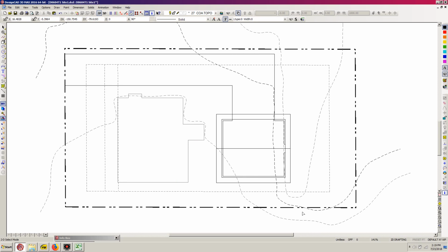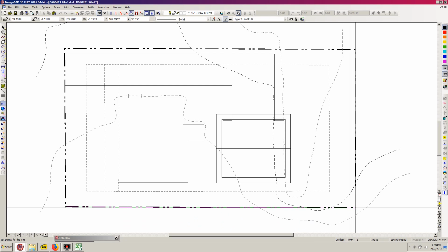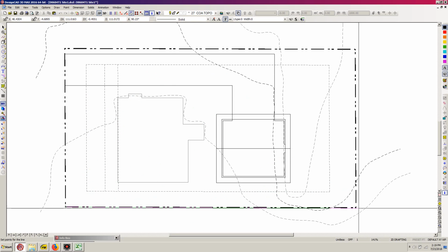The way this lot is configured, I'm going to hit V for vector and right click here on that corner and gravity move to this corner using the comma. And I can tell that up here on the Y dimension, I'll gravity move again, that it is dropped minus 0.288 feet on the eastern end. So that means that's my southernmost point of the lot.